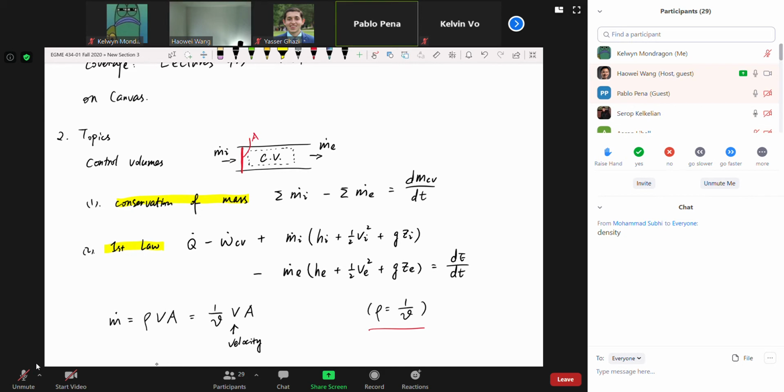Superheated. Table A4. And when you use table A4, you have to have 2 inputs. Usually those 2 inputs are temperature and pressure. And then what if it is a mixture?